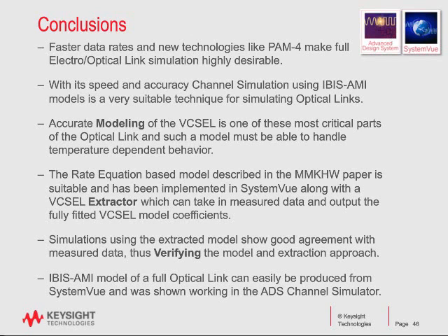Accurate modeling of the VCSEL is perhaps one of the most critical parts of the optical link, and you need a temperature-dependent model for that. The rate equation-based model in the paper that we have implemented, along with our extractor, which takes the burden off of you for developing the correct extracted parameters, really enables you to work with the VCSEL and measure data and get good answers.